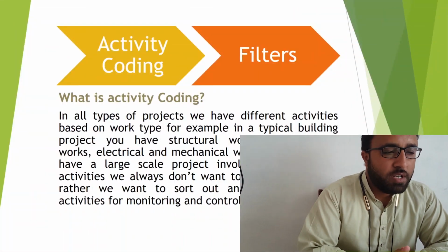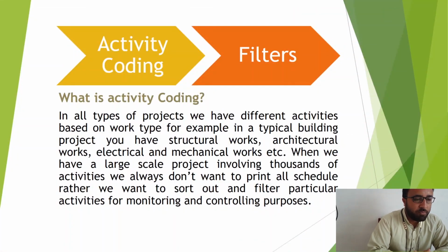That topic is activity coding, and we will see what activity coding is and the different filters that we will use to filter out specific activities related to some specific work or some specific area, or milestones, or in-progress activities, or look-ahead filters. So let's begin today's topic: activity coding and filters.